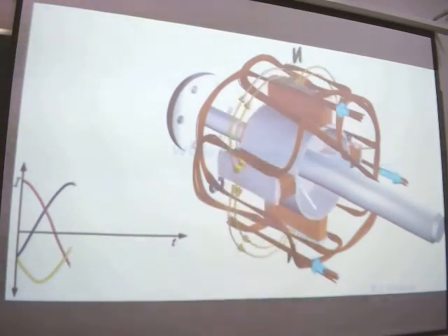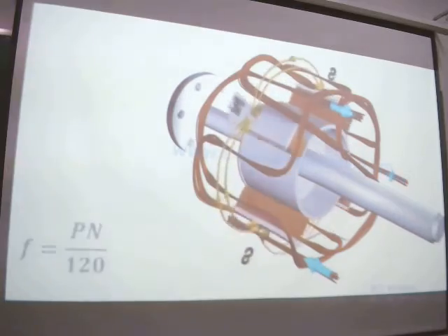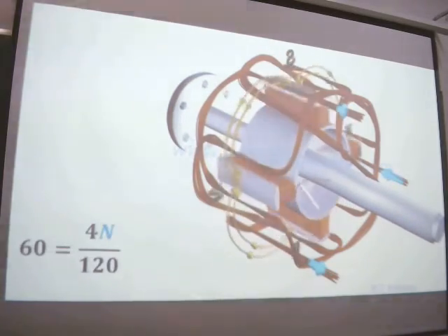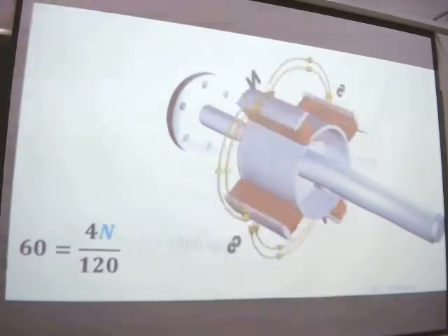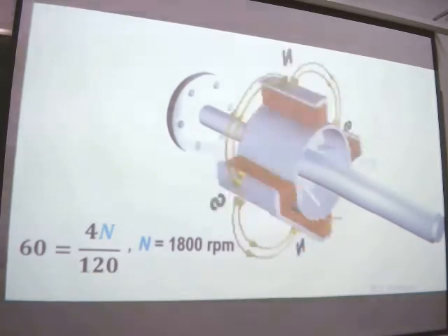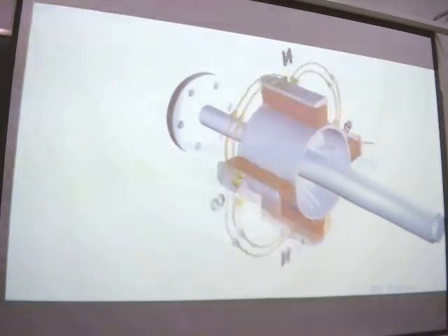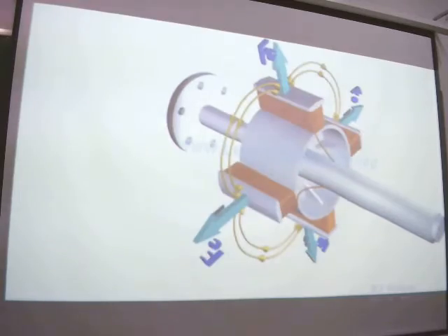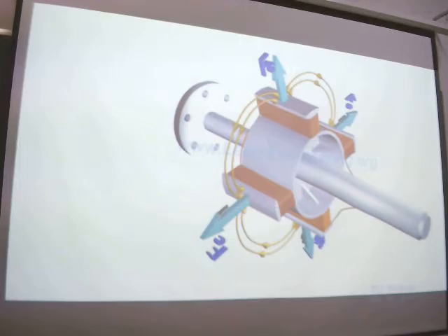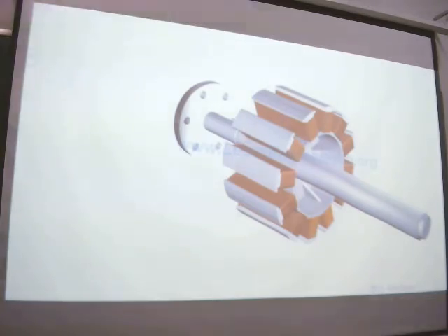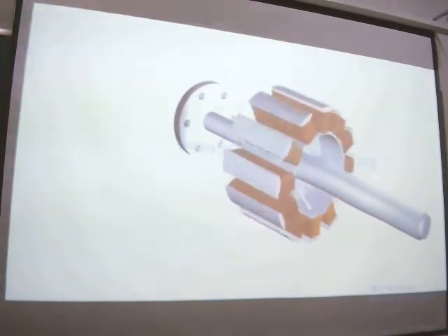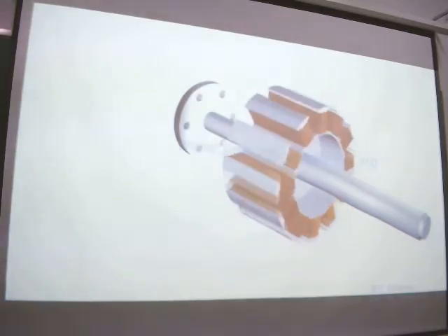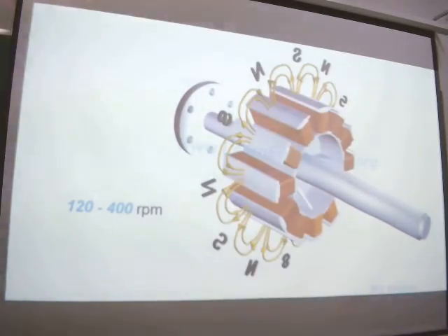It is clear from this equation that in order to produce 60 Hz electricity, a 4-pole rotor should run at the following RPM. Such huge RPM will induce a tremendous centrifugal force on poles of the rotor, and it may fail mechanically over time. So salient pole rotors generally have 10 to 20 poles, which demands lower RPM. Or, salient pole rotors are used when the prime mover rotates at relatively lower RPM.